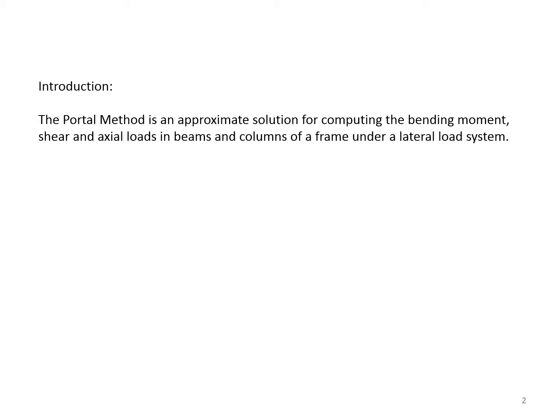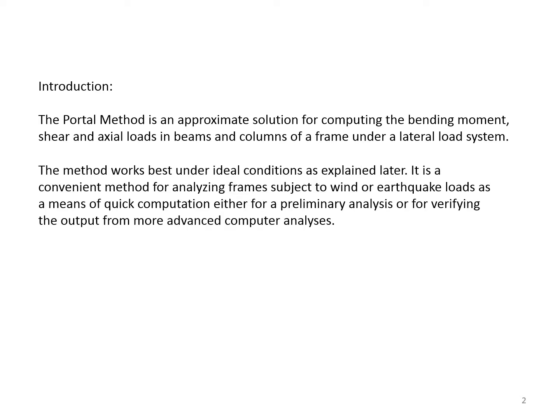The portal method is an approximate solution for computing the bending moment, shear, and axial loads in beams and columns of a frame under a lateral load system. The method works best under ideal conditions as explained later. It is a convenient method for analyzing frames subject to wind or earthquake loads as a means of quick computation, either for a preliminary analysis or for verifying the output from more advanced computer analysis.